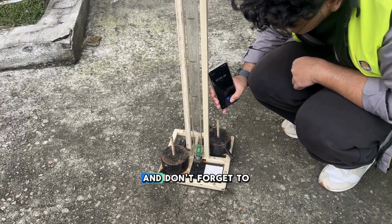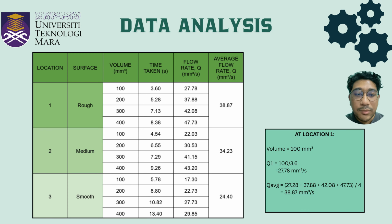Next is the data analysis for the outflow meter test. We use a fixed water volume of 100 cubic millimeters and measured the drainage time. The outflow rate was then calculated using Q equals volume divided by time. At location 1, the first reading gave an outflow rate of 27.78 mm3 per second, and the average outflow rate was 38.87 mm3 per second. The higher outflow indicates better drainage, reducing water accumulation and the risk of hydroplaning.